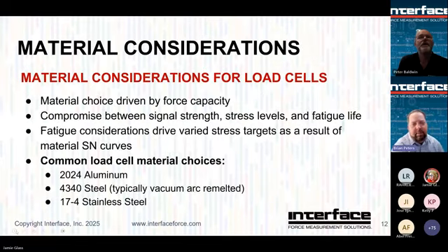Speaking from a load cell standpoint, load cells are built from several different materials. Interface's common materials are aluminum, steel, and stainless steel, listed below. But it's usually going to be a compromise. A load cell is designed around how we provide the highest signal, the best measurement, while still accommodating the desired force levels.